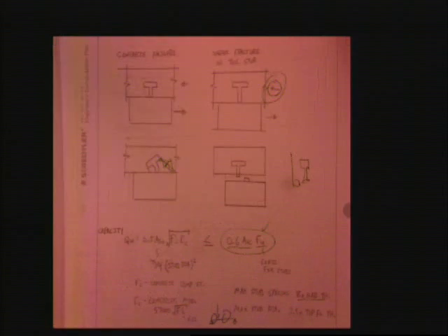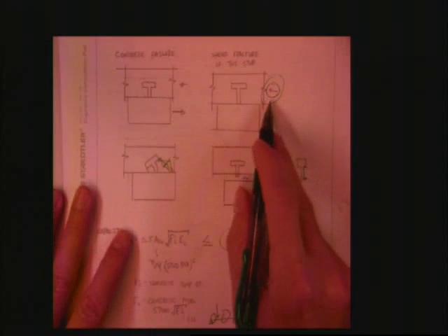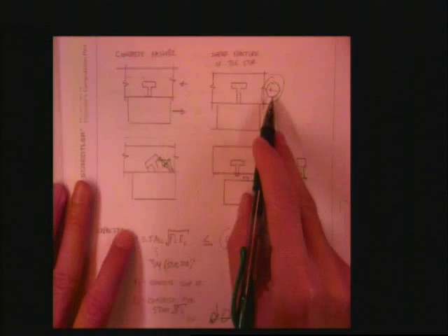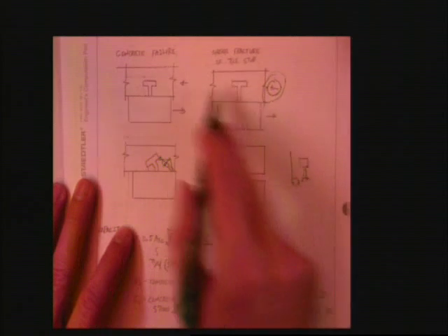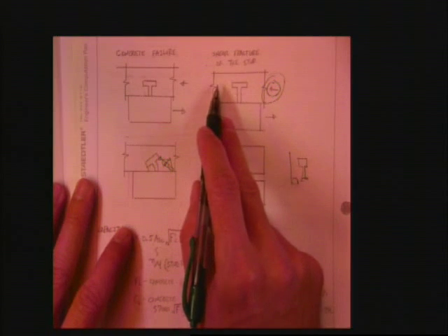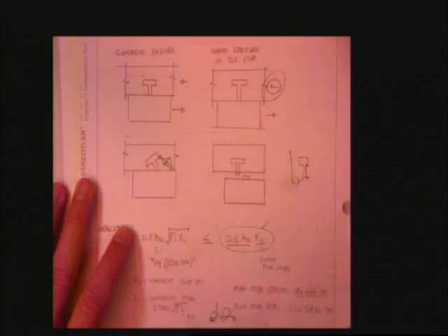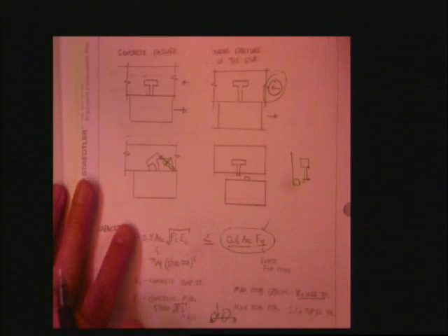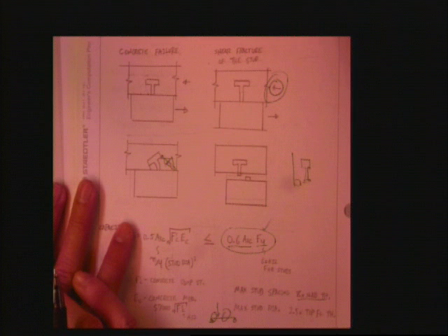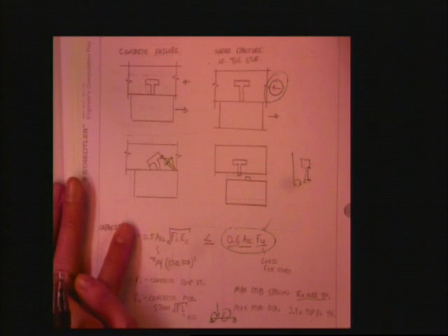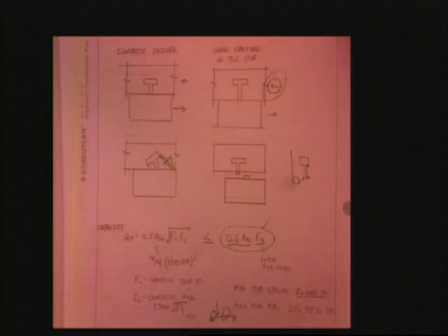That's actually only half the story when you do this, right? Because you're going to have to provide that same amount of studs on the left-hand side of that point and on the right-hand side of that point, right? Wherever that maximum moment is, or wherever that point is that you're designing for the maximum amount of studs, okay? And those studs can be equally distributed. You don't have to have them clustered in certain areas, okay?